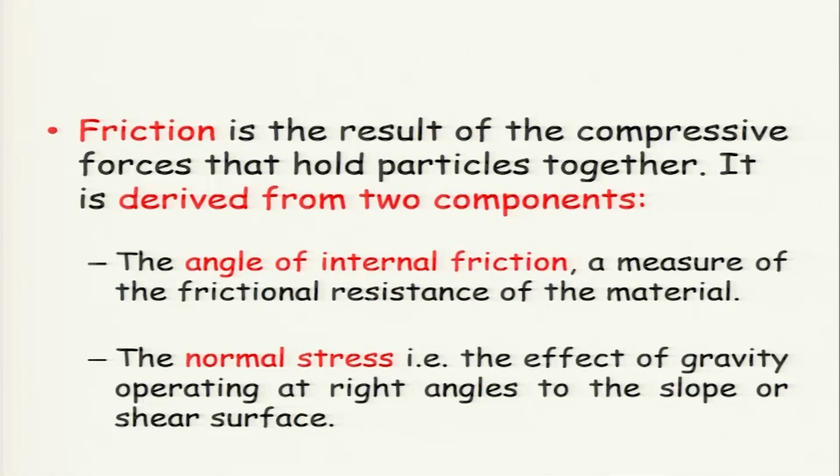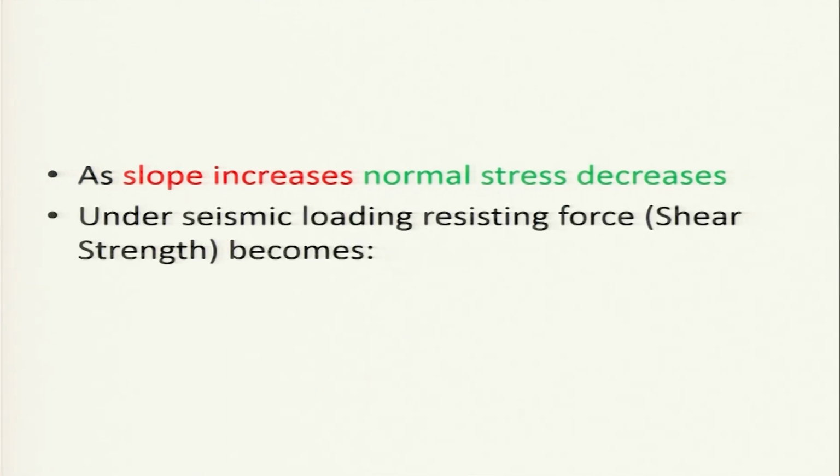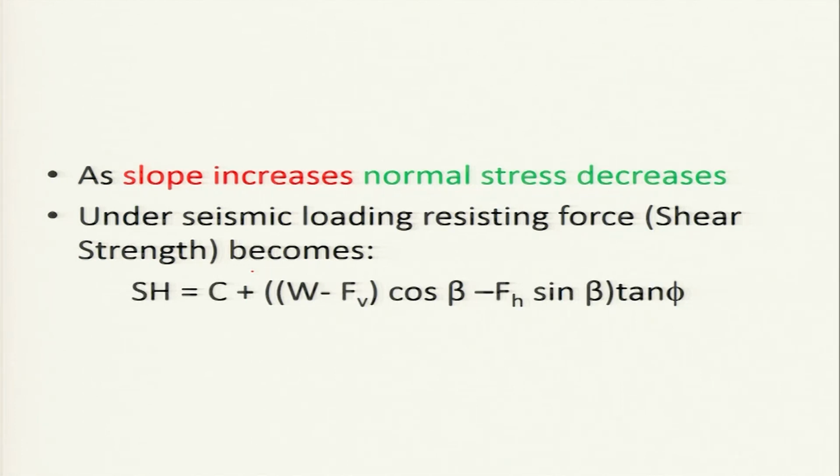Now, as soon as you add water and all that, this will change actually. So normal stress will also change, and of course the strength of the material will also change. As slope increases, normal stress decreases. Under seismic loading, the resisting force, that is your shear strength, becomes as given below in this equation.